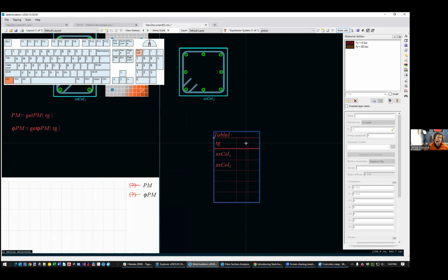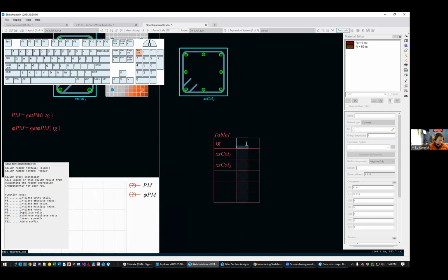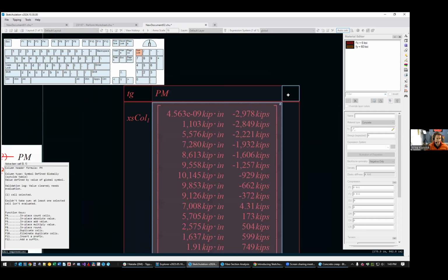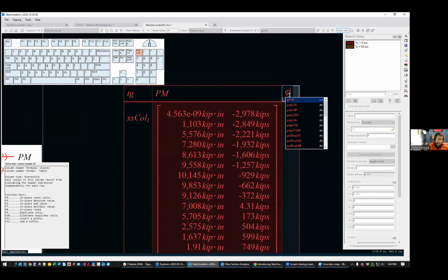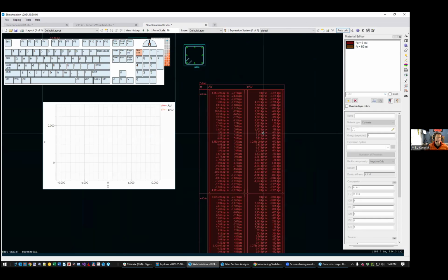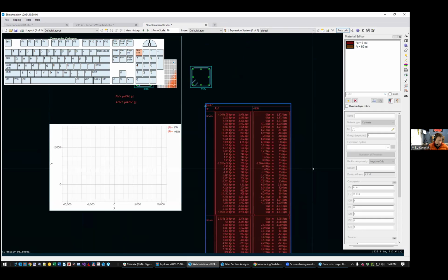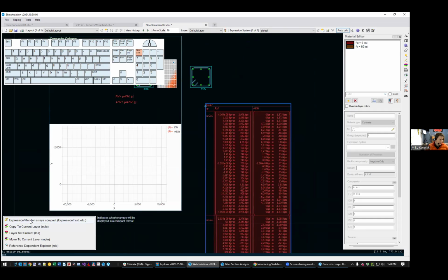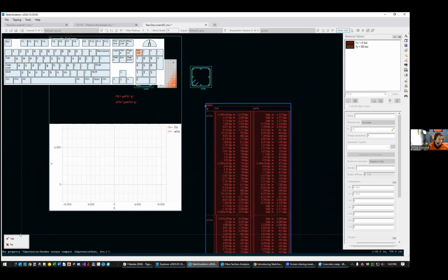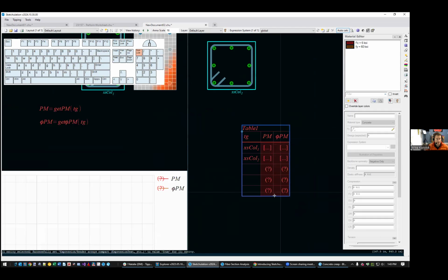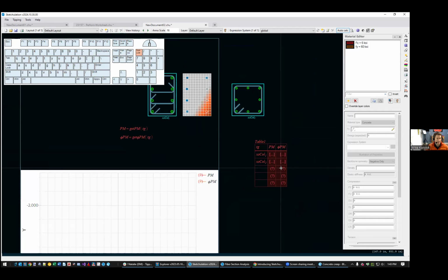And so now inside the table, I just type PM, and we get all the data right there in the cell, and say ePM, and all the data is right there in the cell, and we don't like to see that really, so we select the table and we type this command that says render arrays compact. We want to say yes, so that we know there's data in there, but we don't need to see all the numbers. Unless you wanted to, you could look at it carefully.